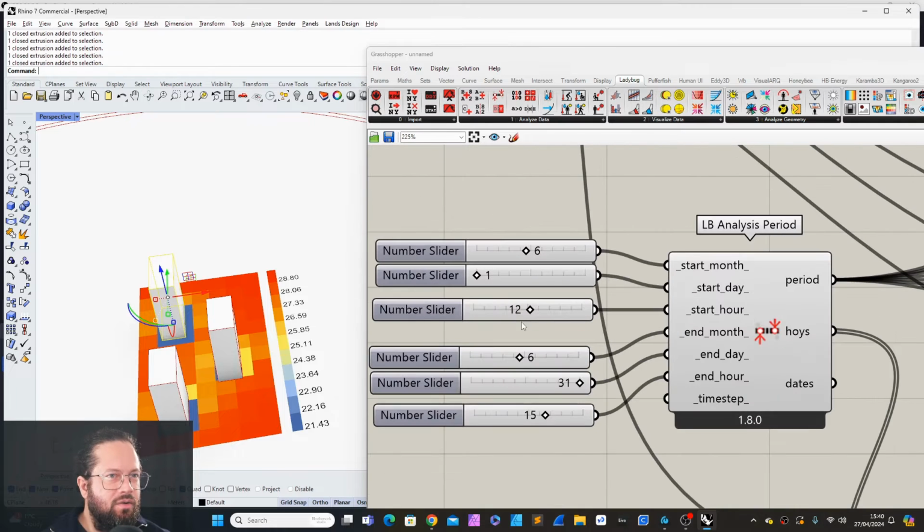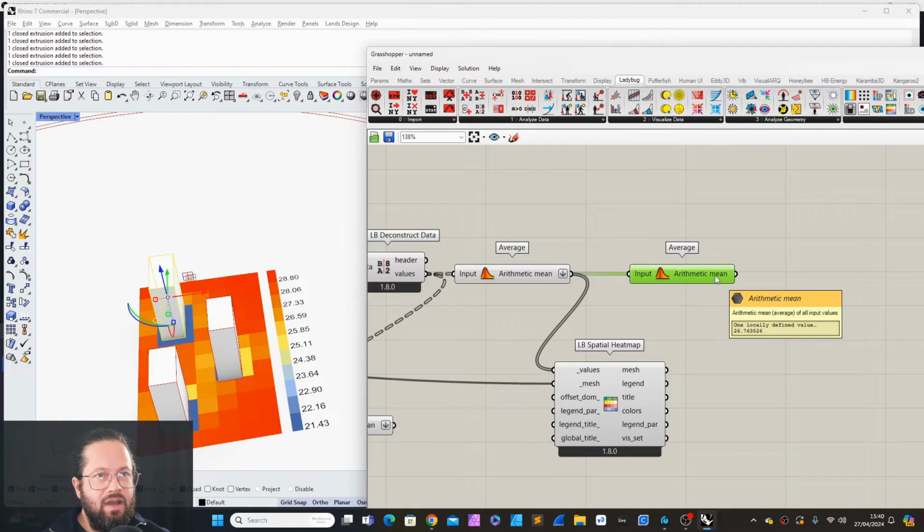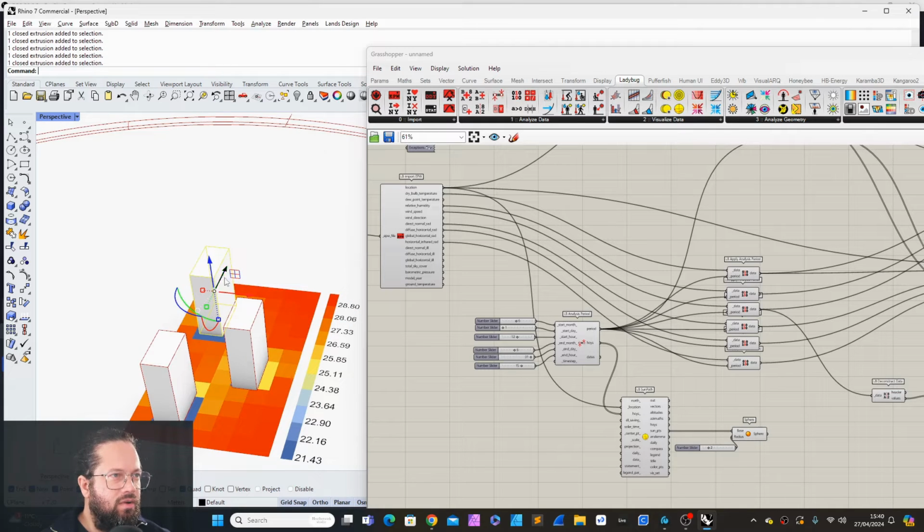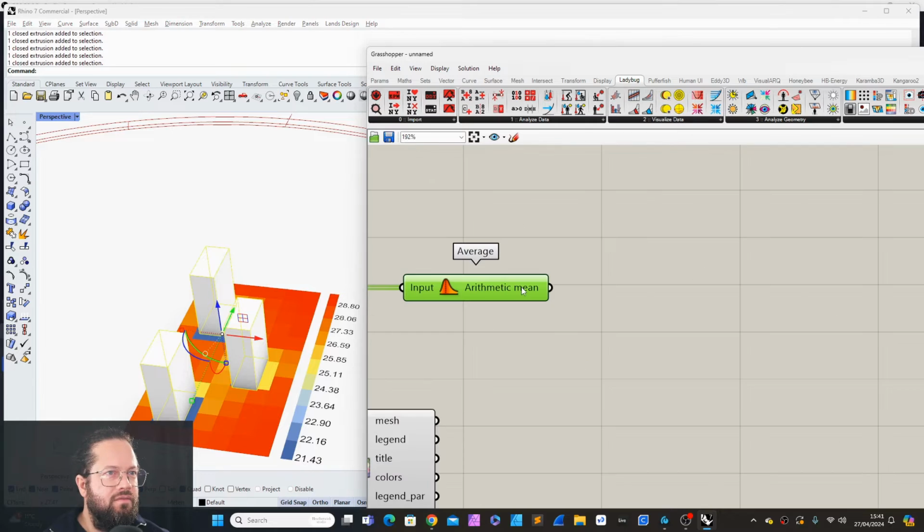Only areas around the building here would be more suitable, I would say. But we're testing only a few hours, only from 12 to 3. This is only 2-3 hours. Nevertheless, we have 26 here, which is slightly above that. Now, what we could do is argue, okay, this is our massing. We have a certain design we need to follow, but we could shift the buildings around on the site to see if we could optimize this number towards 21. Now we have 26. Can we optimize it so it moves towards 21?